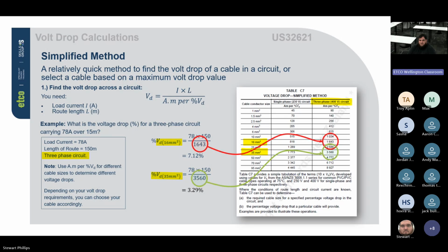So we're not applying enough pressure to push the current through, and we can damage sensitive equipment or just general appliances. Cheap appliances won't run very well on lowered voltage. Some will. If you notice on a lot of the appliances, like heating appliances, it'll say 220 to 240 volt, so it allows for that voltage drop and spike. But yeah, not all appliances are created equal.